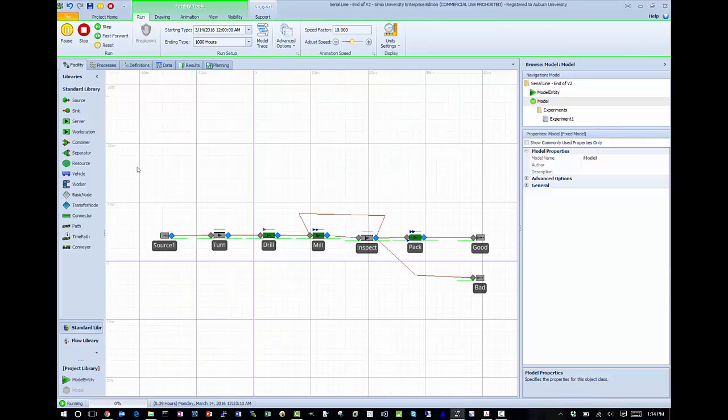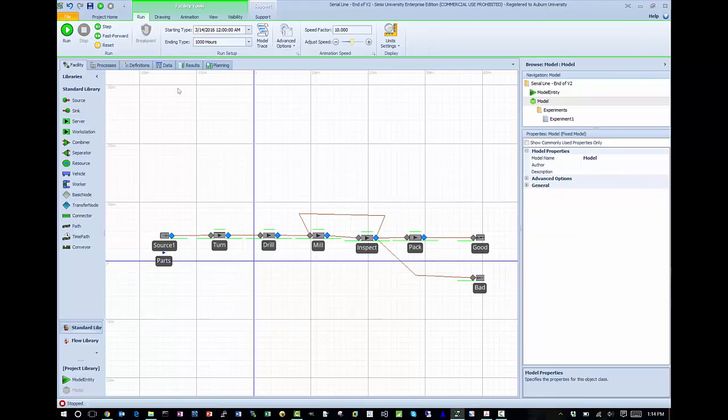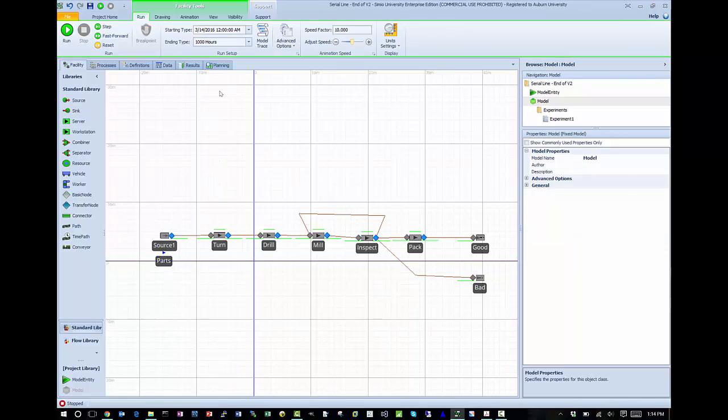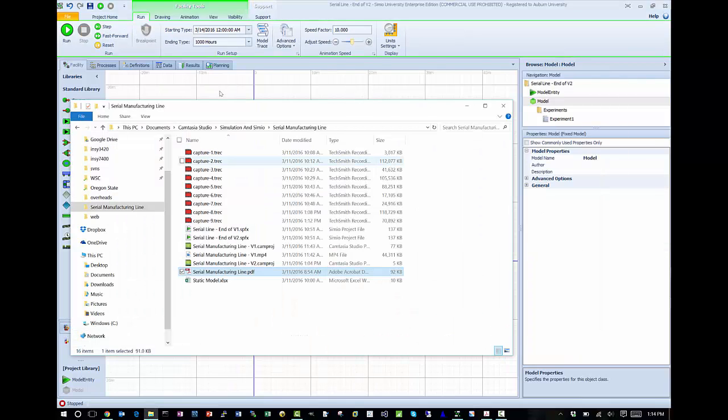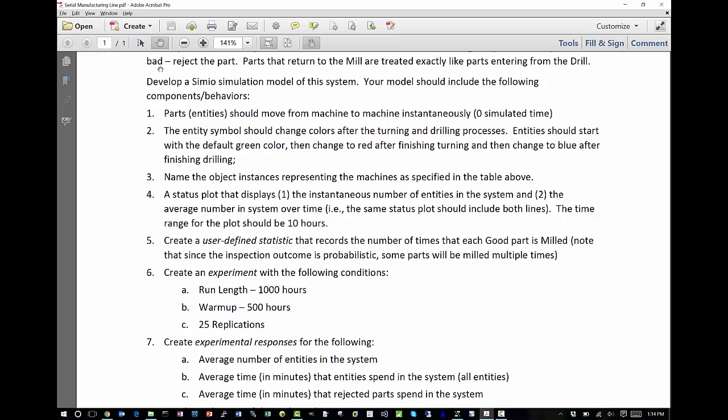So just to review, what we had to do in order to change the symbol is update the symbol list to add our additional symbols, and we modified their color. Then we used the current symbol index property, entity picture, and then we assign the value at the location in the model using state assignments.